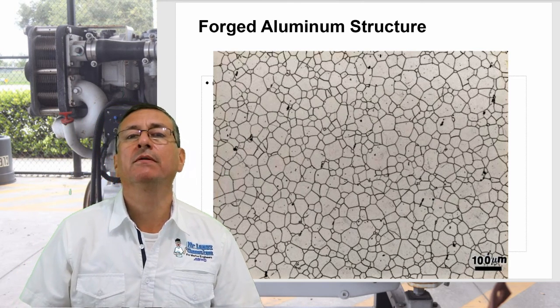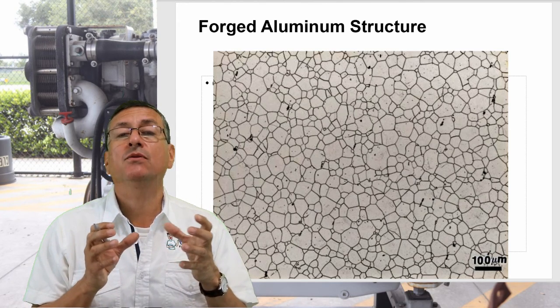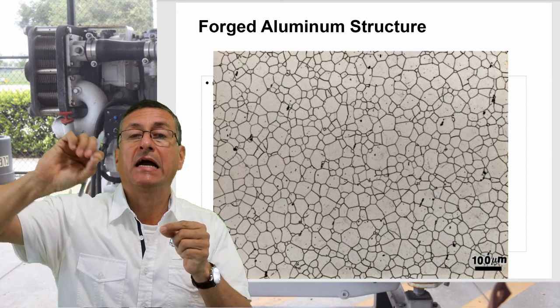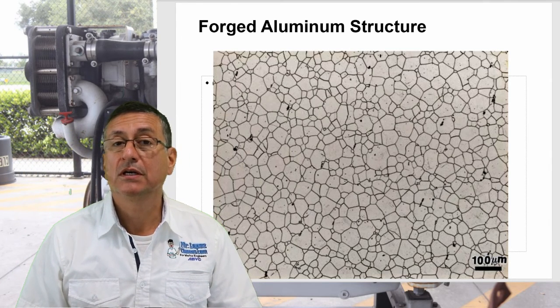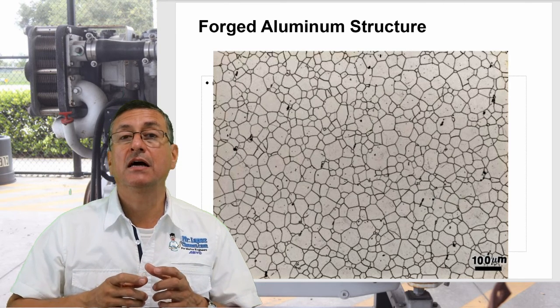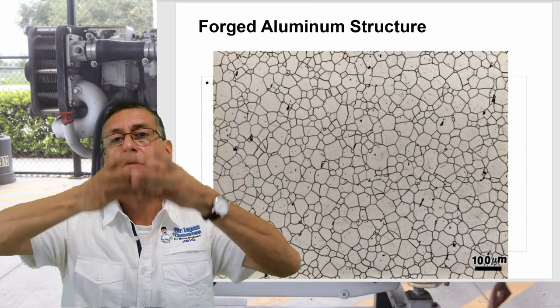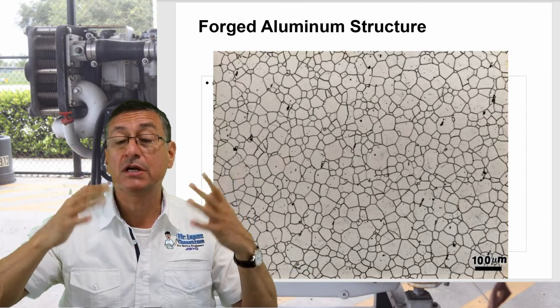Yeah, this is the problem. The air inside of those structures expands with the temperature and propagates cracks. This is not good, especially in elements like the piston. These are elements that are in cycling operation up and down at high pressures and high temperature.